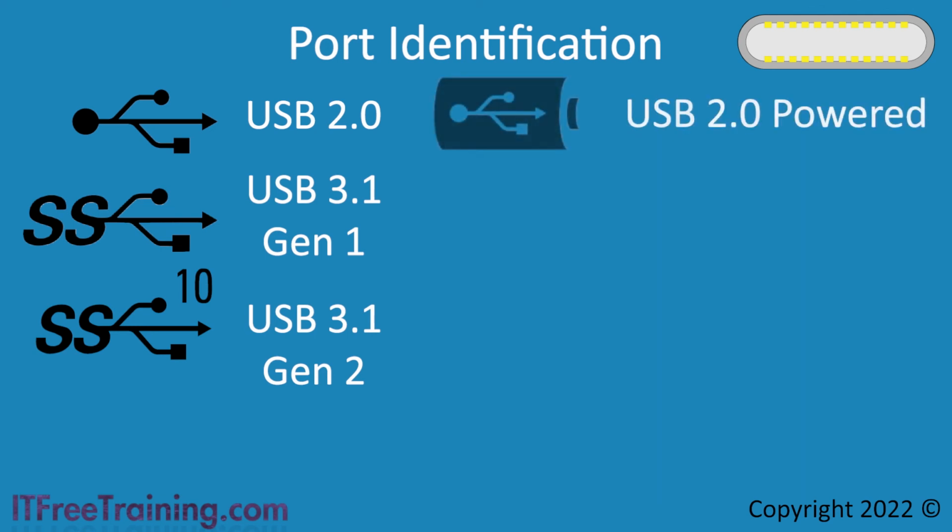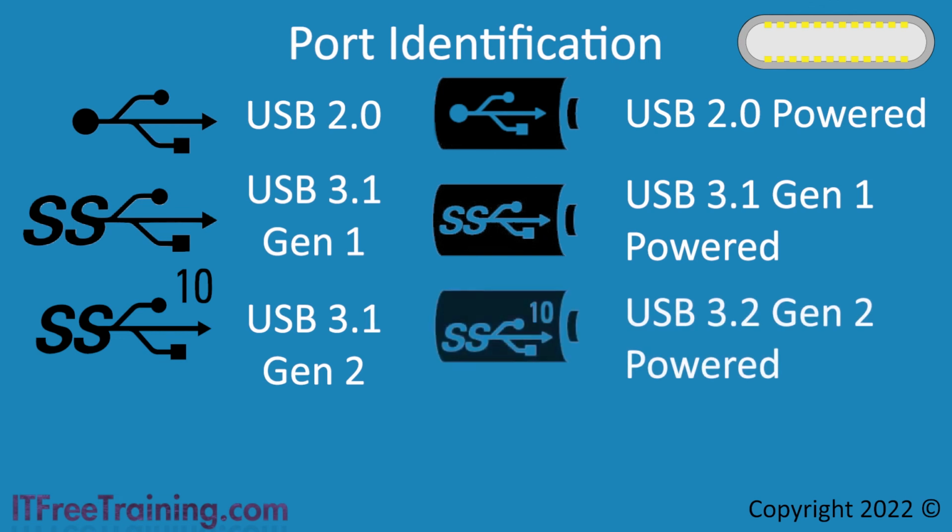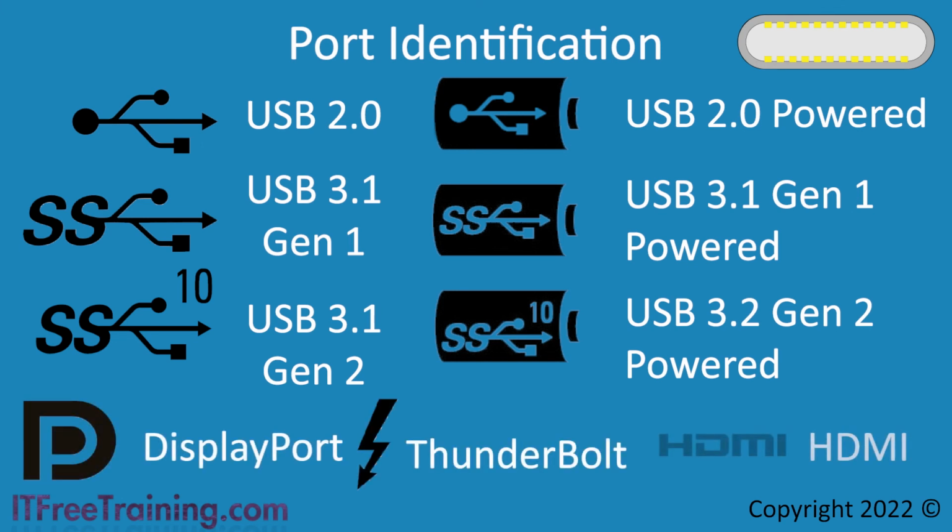If the USB port is powered, the USB logo may be different. I say maybe because there is no guarantee that the logos will be the same on different devices or even be present at all. The port may also display logos to indicate which kind of graphics port it supports. Although this may seem complex at first, the point to remember is that both sides only need to support the same thing. Both sides will negotiate to determine what will be used.